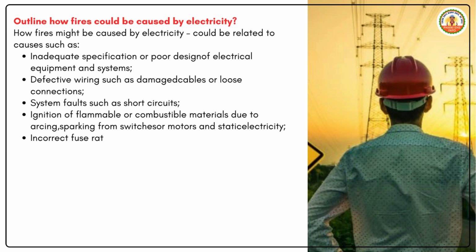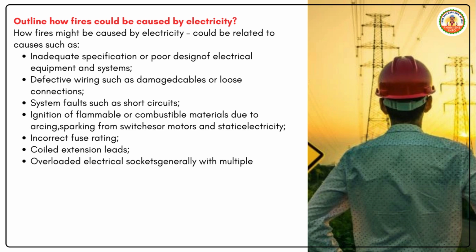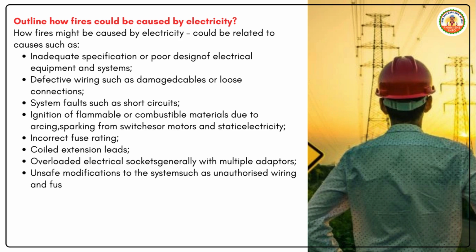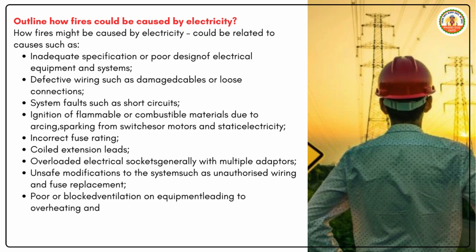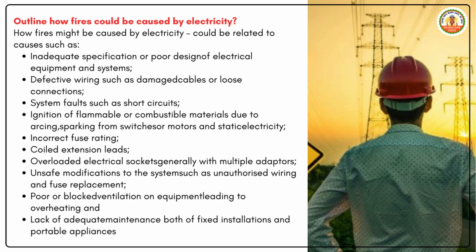Incorrect fuse rating. Coiled extension leads. Overloaded electrical sockets, generally with multiple adapters. Unsafe modifications to the system such as unauthorized wiring and fuse replacement. Poor or blocked ventilation on equipment leading to overheating and lack of adequate maintenance both of fixed installations and portable appliances.